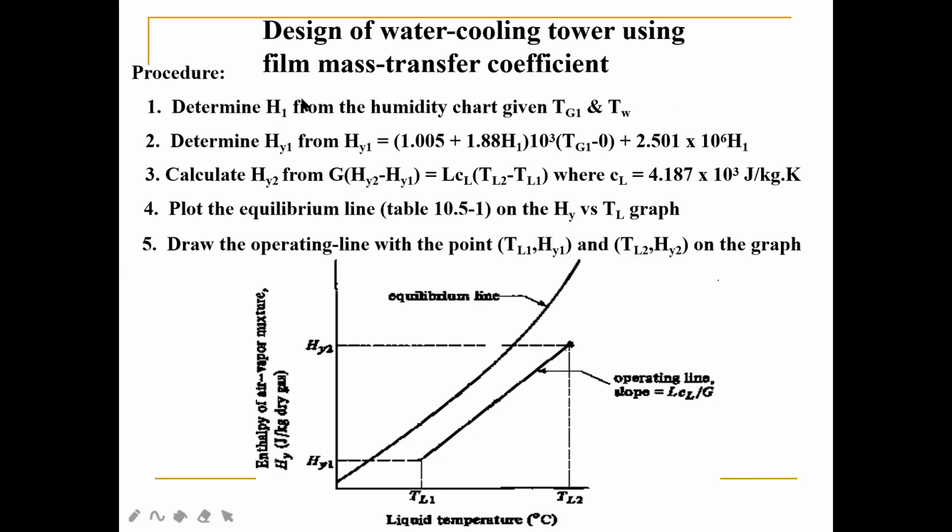Okay, from that H, you can calculate the enthalpy, which is the HY. And this is the equation for you to calculate HY. If you notice, you will put the H1 you find from step number 1 into this equation for HY. Okay, once you get the HY, you will use the HY1 you calculated from step number 2